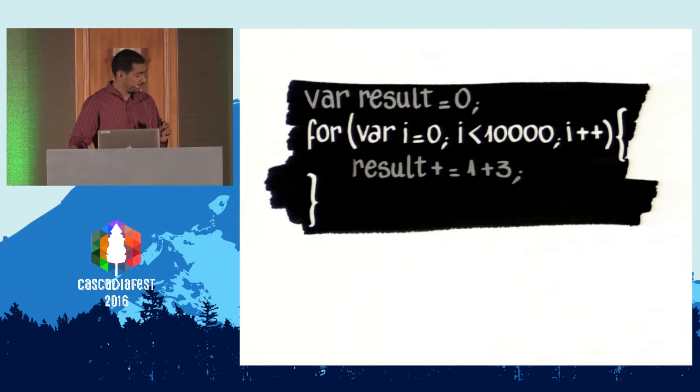In low-level programming languages, calling a function would end up in a context switch. For example, just after calling the function we will have to save all the current status or push all the registers to the stack, and before returning, it would have to resume the previous context, popping the saved registers from the stack.